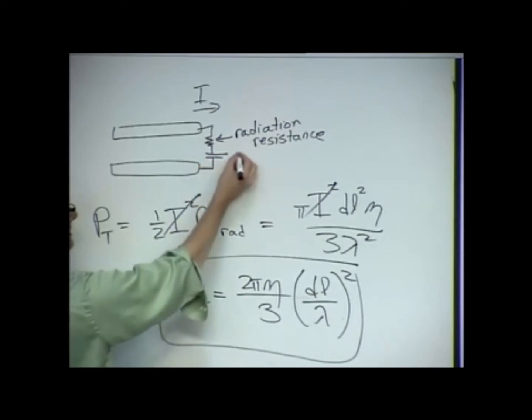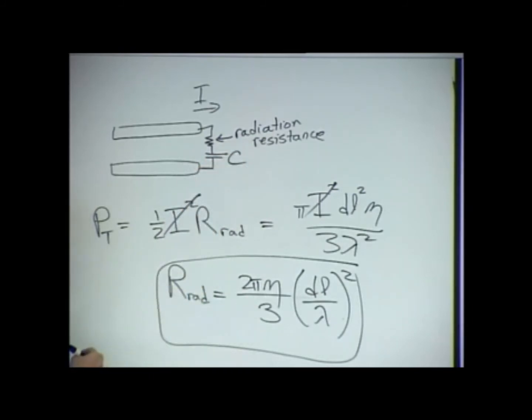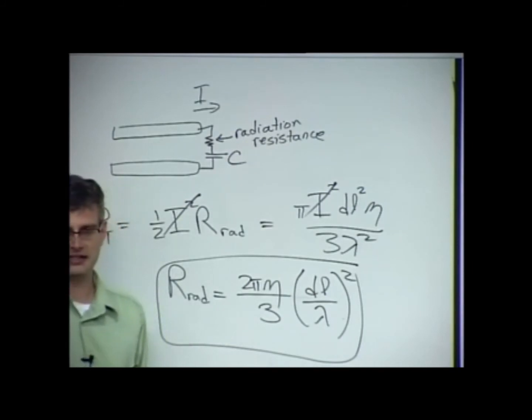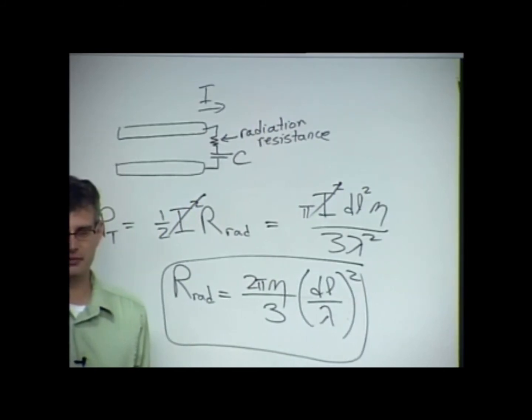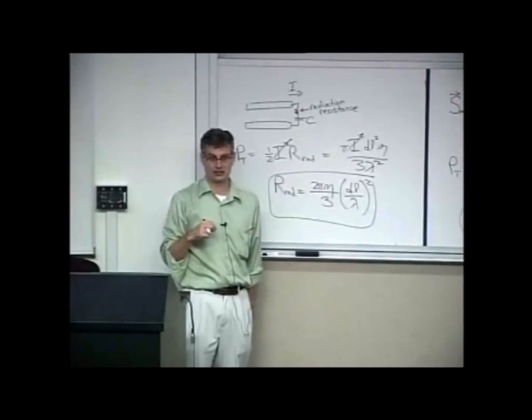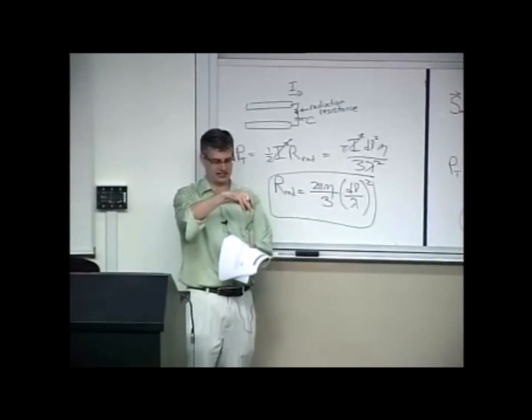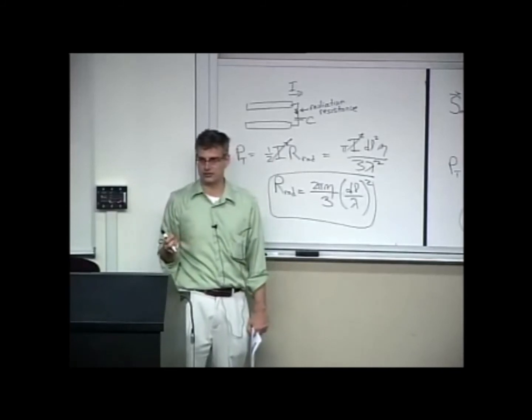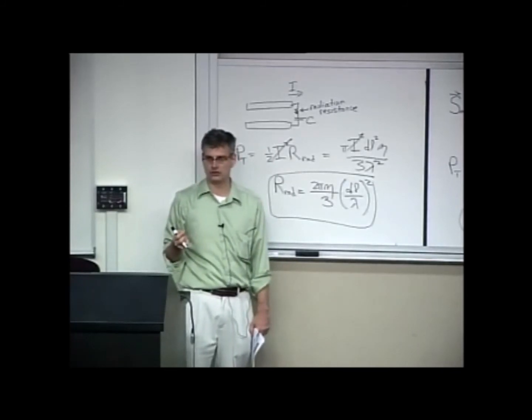There's also going to be a C, a very, very large C, because this is a highly capacitive system, because it's not resonant. I'd actually need to get a real value impedance for a pure radiator like this. I actually have to get this thing to stretch out in space to at least a half a wavelength, right? Got to have a half-wave dipole.